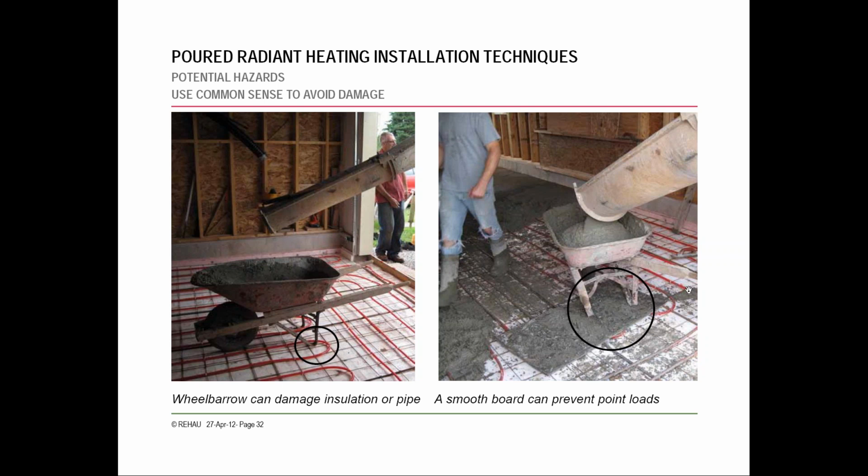The pipe is extremely resistant to damage. Most PEX are. This specifically in this picture is the PEX A, so it's got 80+% cross-linking. It's very, very durable and hard to beat up. And if it kinks, you can unkink it with a blowtorch or a heat gun, preferably. But again, we'll get to some of that later.